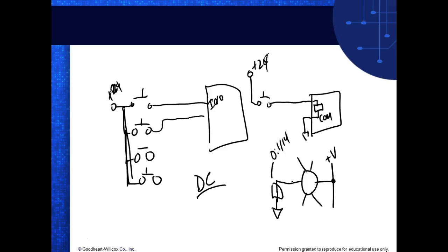When you go in and create a new program on a modular PLC, what do you have to specify? You not only have to specify the processor, you have to specify what type of module you have in each slot of that rack, right? You understand? It should be on that too. But like I said, every module I've ever seen specifies inputs or outputs. It specifies whether it's sinking or sourcing. Your fixed PLCs is where you're probably going to have to look it up in the data sheet.